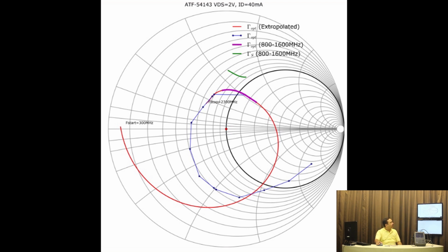And as you could see, they are not exactly on top of each other but fairly close, such that for practical purposes we could use that, because when you do a practical design you are limited with the choice of inductor values. You could have many choices in terms of capacitor values, so you have to think of all those practical aspects as well.